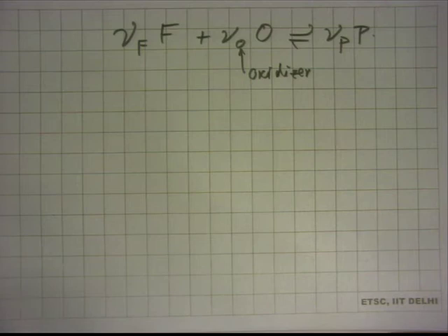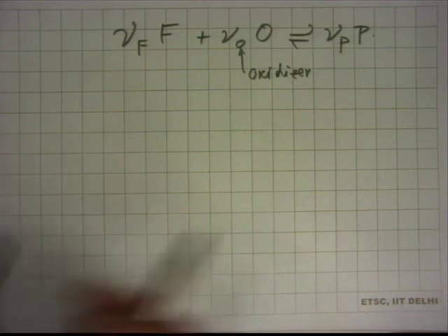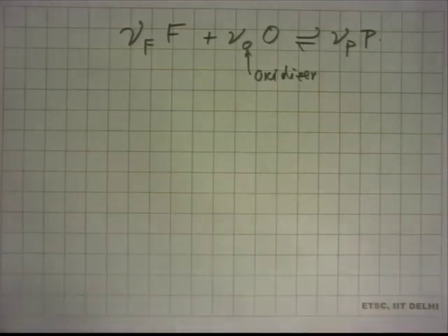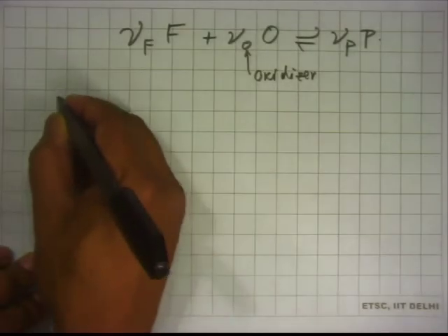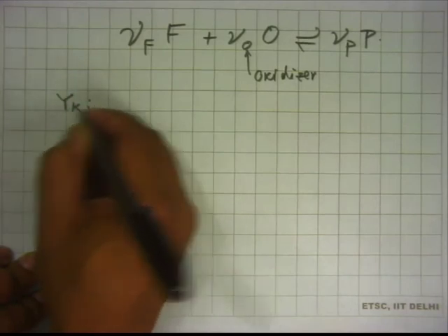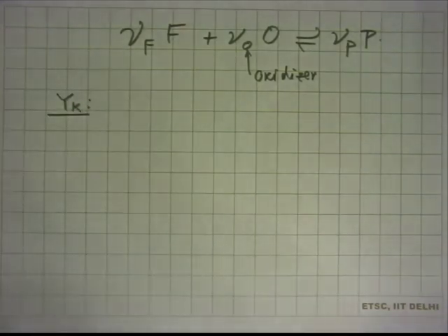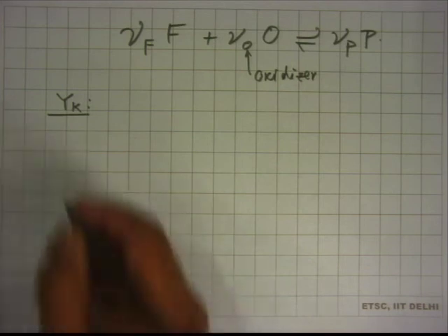I didn't tell you another difficulty. I'll give you some conservation equations, essentially without deriving, but I trust that you will be able to follow this, because we have some idea about combustion conservation equations so far. So, let us write the conservation equation for species Yk, not writing Yi, writing Yk, Y for mass fraction, k for the kth species.